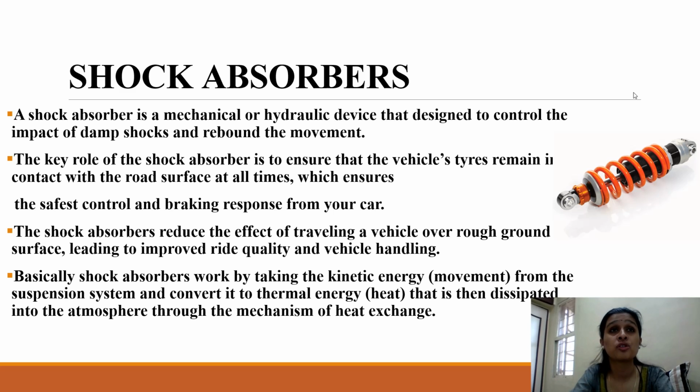So the ultimate output of any suspension system are the shock absorbers, or solenoid motors, or the braking systems, or air compressors. So what does a shock absorber do? Basically, a shock absorber is a mechanical device, or a hydraulic device, designed to control the impact of dampening shocks and the rebound movement. The key role of the shock absorber is to ensure that the vehicle's tires remain in contact with the road surface at all times and at all speeds, assuring the driver that you are driving safely.